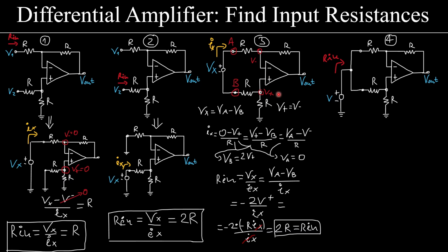This requires practice. For your exams, you will have a very hard time remembering this if you see it only once. All right. In your exams, you will probably have a resistance value here and here and here and here, all right, of 100 ohms, 200 ohms, etc. So you cannot just say that Rin is equal to 2R, right? This will not hold true in any other case. This holds true only where these resistances are all of the same value.